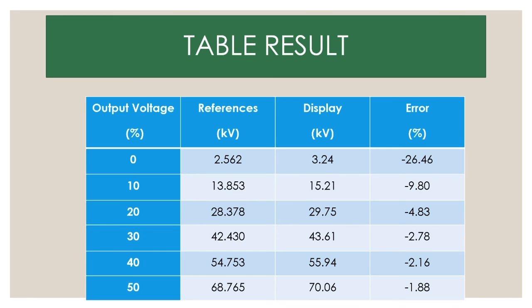Of course this is because the surroundings of the experimental setup can affect the reading, and also because an increase in surrounding temperature can decrease the sensitivity of the equipment itself. The accuracy of the graph produced on the picoscope also depends on the sampling interval that we set earlier.